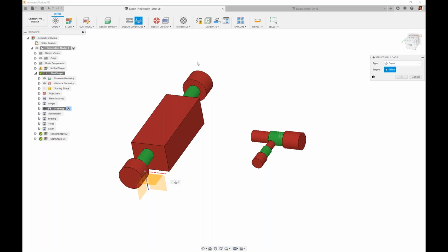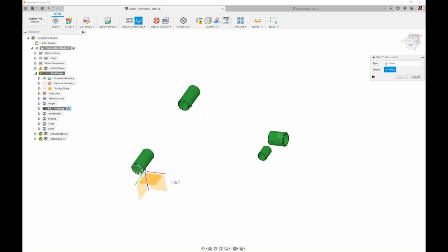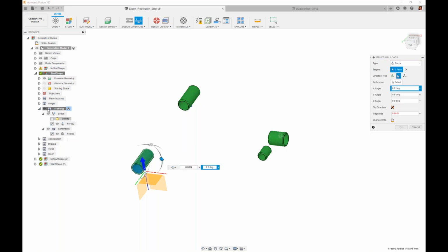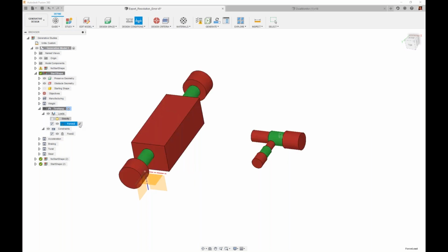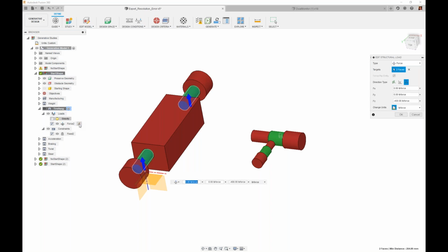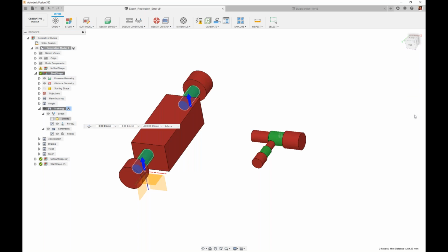There's no specific requirement that says for a given load case you can only put a single force on a given face or a given edge. So while I have these 2 faces with a given force, I could put another one in there to represent a remote load or some other bending action happening on that same face.